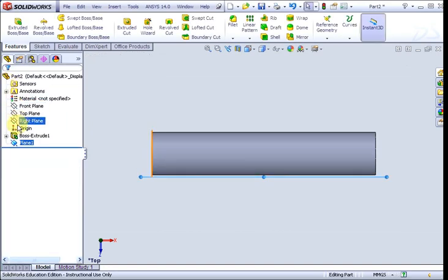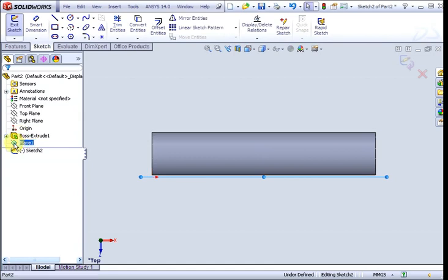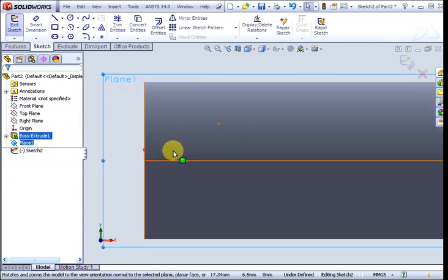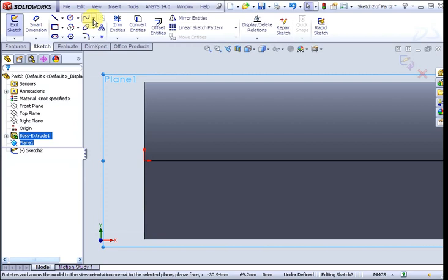Now we are going to sketch inside the plane. So new sketch, you can make it face us. Okay, now you should properly draw the geometry of the cross section using the spline for the outer curve, inner curve, but for simplicity's sake we are using ellipse instead.